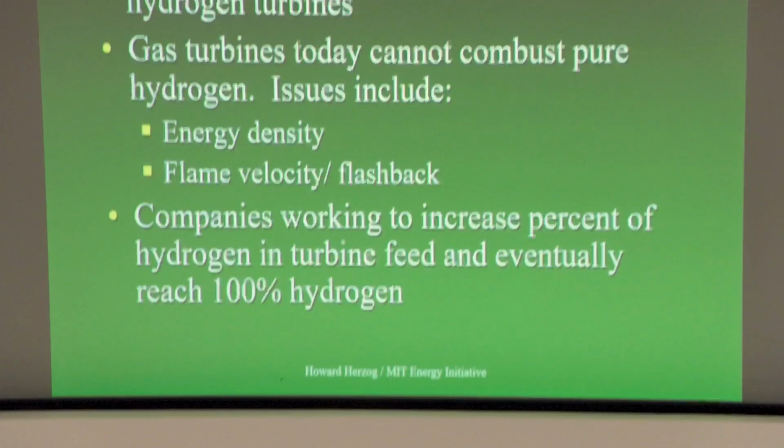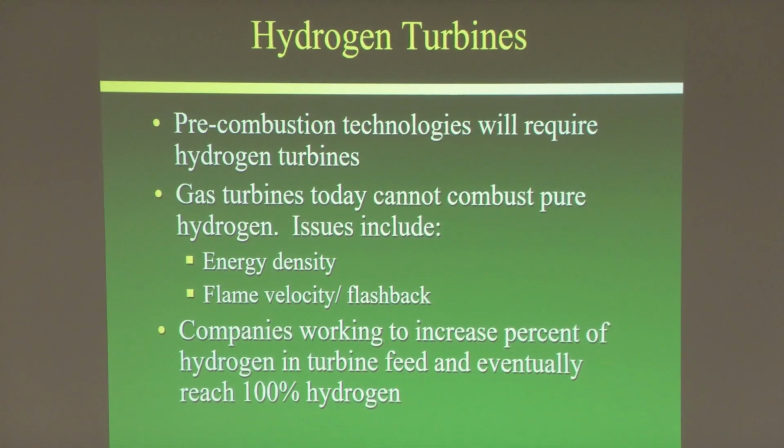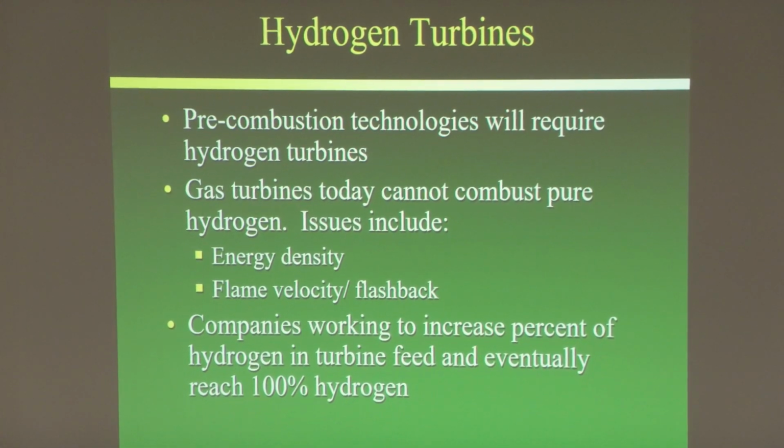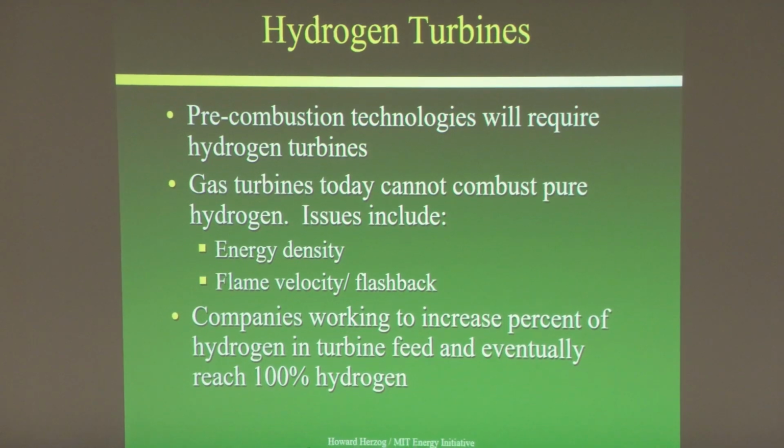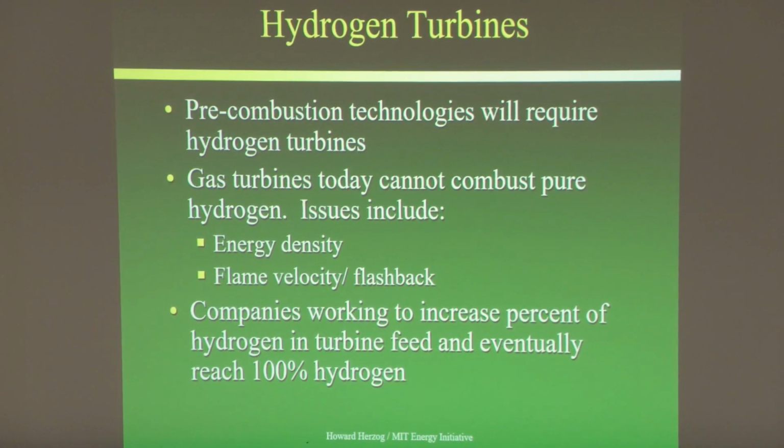First, let me say that we take the hydrogen and put it into a turbine, as I showed here, but those turbines don't exist to take pure hydrogen. There are issues with hydrogen. It has a different energy density than methane, you have different flame velocities, and you have to worry about flashback. But they're working on getting turbines to eventually go to 100% hydrogen.